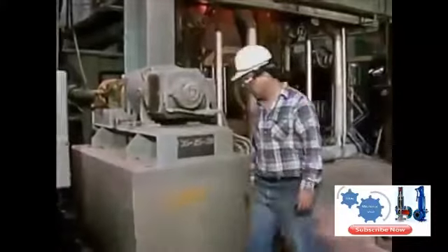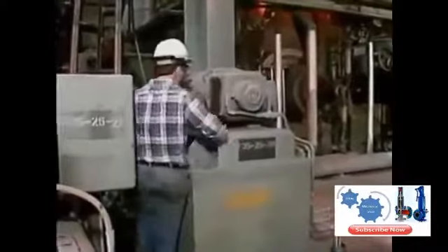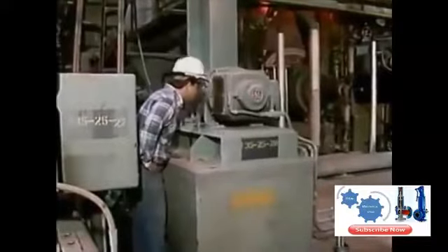Brushes are a frequent maintenance item for DC motors. Because they rub against the commutator, they wear down, so they must be replaced periodically. Sparking or arcing near the brushes or on the commutator can mean that the brushes need to be replaced, or that they're not making good contact with the commutator. In addition, brushes can chip, which impairs their effectiveness.